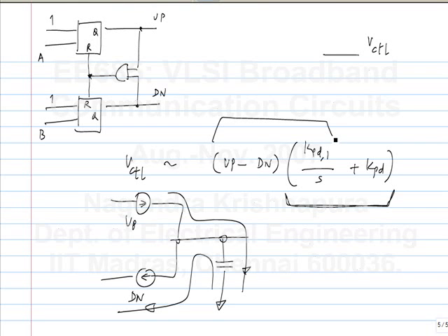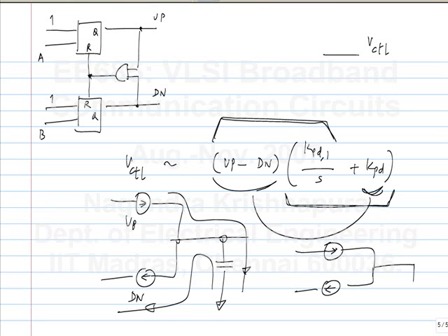R in parallel. Yeah, so how do I realize this? It can be an R in series, right? So, see, if for this I can do this, okay? And if I wanted this part plus this part, I can substitute a resistor for this capacitor, okay? I can have this up minus down current flowing into a resistor, okay? Now I need to add these two voltages, okay? I realize that the same current is flowing through the capacitor and the resistor, so I can just put them in series, okay?